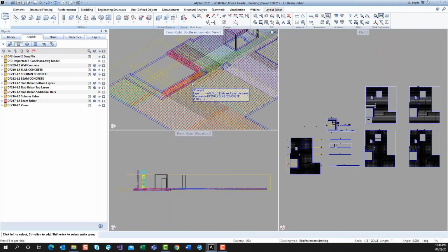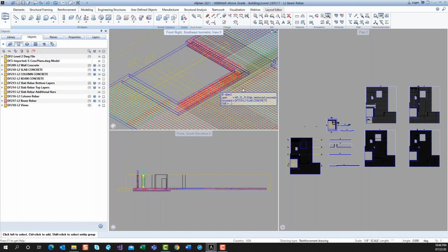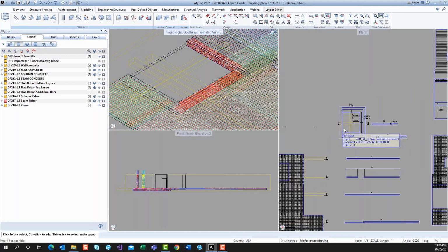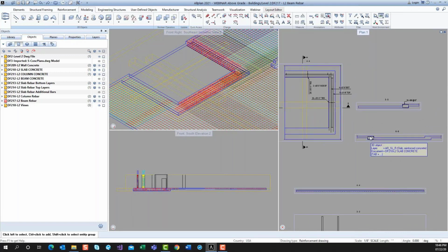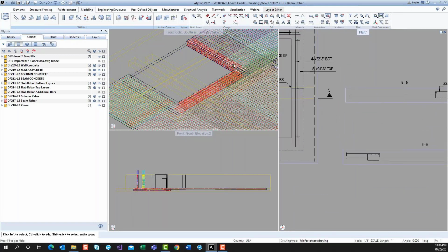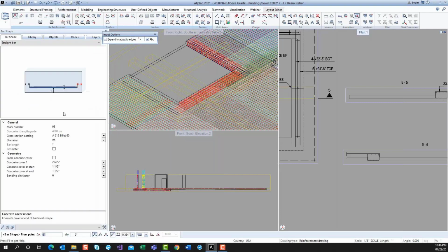What I'm going to do for this next portion, I've got a lower slab here. I want to apply some bars. I'm not going to use my area reinforcement tool. I'm going to just do some general straight bars, pop them in the bottom of there, because I'm doing this with a purpose in mind. I could use the area reinforcement tool, which is fine, but I'm going to pop these in, and then we get a notification from the contractor. Contractor wants to add an opening in this lower slab, so I'm setting that up for this.